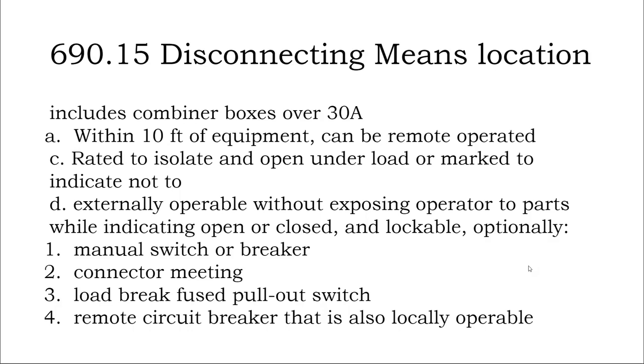You can just run it straight through. But then down the road, being able to disconnect the neutral is nice for truly off-grid systems where you don't want to backfeed. The utility's concerned about you backfeeding during a power outage. Being able to disconnect fully from the grid by disconnecting the neutral as well can be useful.